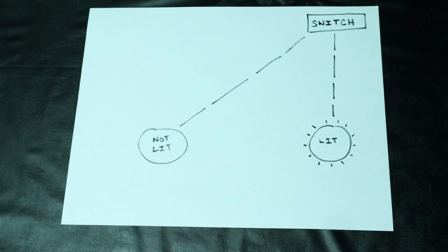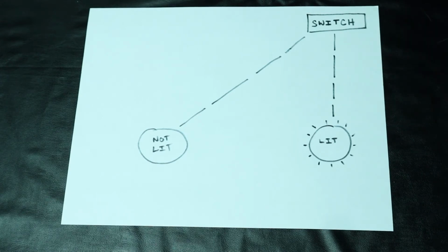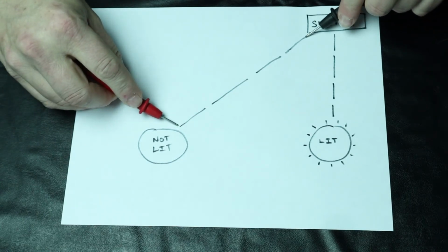Now, what's the point to all of this? What's the purpose of checking for continuity? Usually a person will check for continuity in order to diagnose a problem with an electronic circuit. For example, a vehicle may have only one headlight working, and I've ruled out the switch being bad because one headlight still works. After replacing the bulb in the headlight that's out with a known good bulb and discovering that it did not solve the problem, I can use a multimeter to check for continuity in the wires that connect the bulb to the headlight switch.